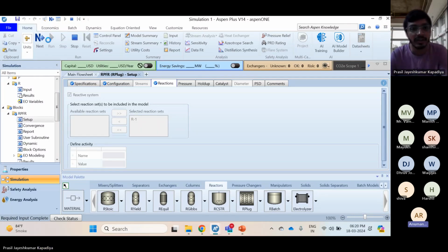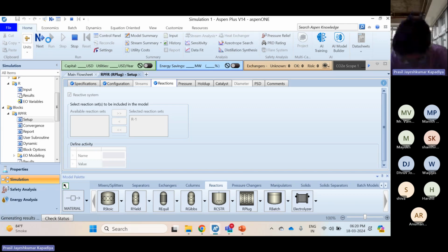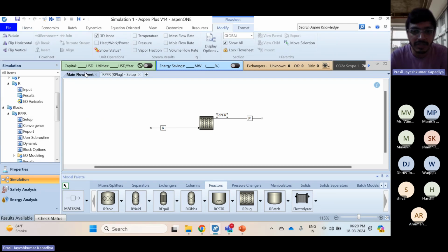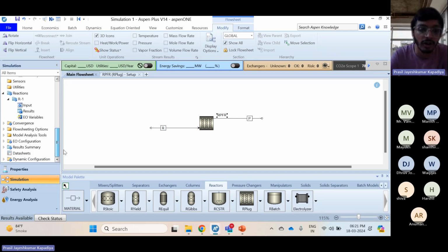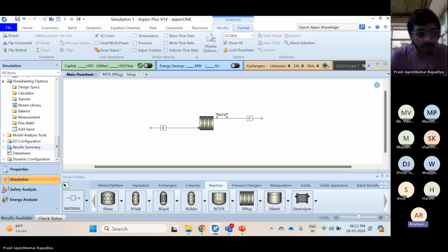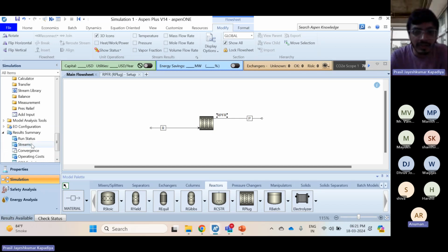Sir, adsorption reaction is not in this section. There is no adsorption. No, we'll not. We are adding it under driving force, not under adsorption, because it's a reaction. So for reaction, we will need to add those exponent factors, basically the order of reaction. I guess that option is not available under the adsorption term, similar to power law.